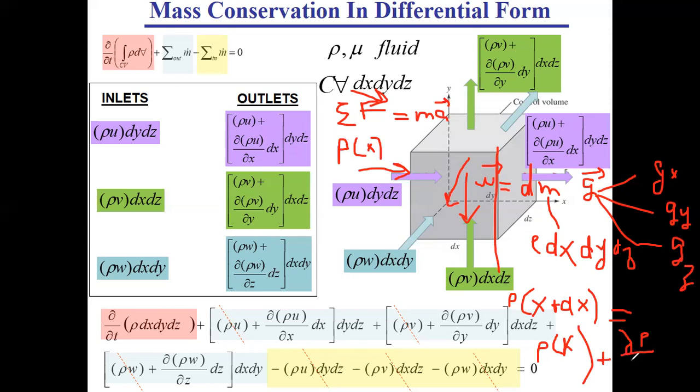And as you can see already, the problem is very complex because I have the velocity that is unknown, the pressure field that is unknown, and I want to couple these. I want to relate pressure and velocity. This is why, as we'll see in this course, we have coupling algorithms between velocity and pressure. We'll see how we can use them to correlate pressure and velocity. So at this face, the pressure is Px plus del P by del x dx.